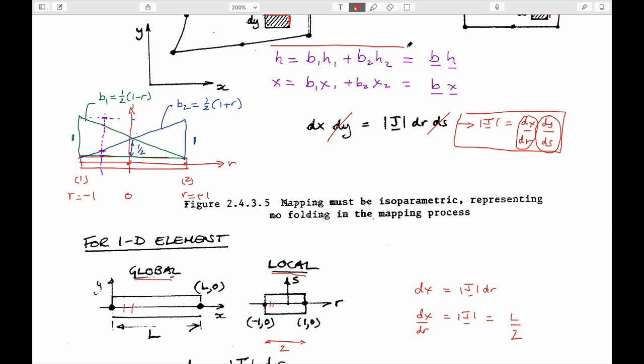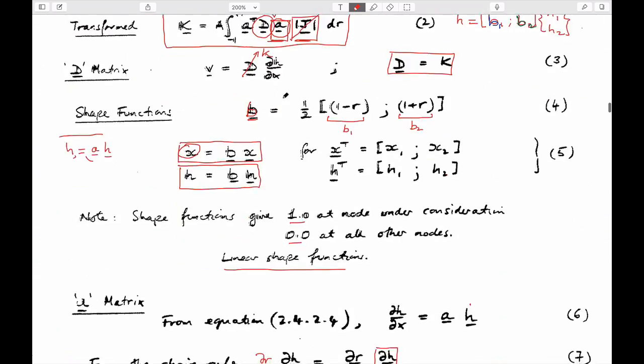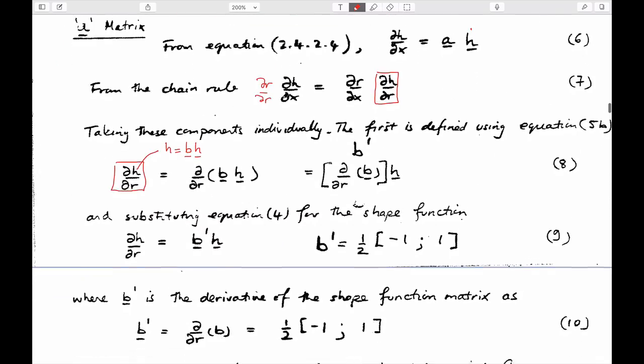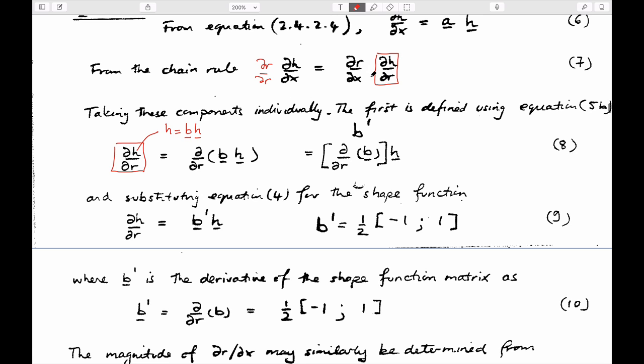Depending on how you like to think about this. And so what we can do, if we want to know what this second term, first, I guess, call this term 1. Term 1 is we can substitute into this for the heads at any particular location being a function of nodal values, which only exist at the nodes, and shape functions, which are just values which map it. And if we do that, this is this expression here for this.